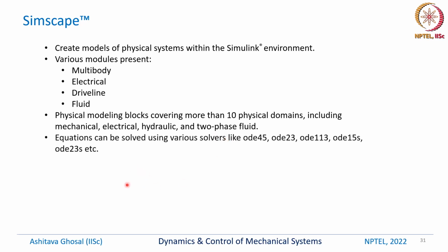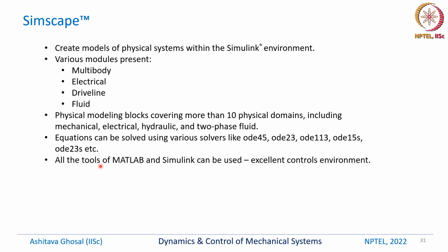The equations can be solved using various solvers: ODE45, ODE23, ODE113, ODE15S. This is a stiff solver. ODE23S is also another stiff solver. You can pick which solver you want to use to solve your particular model. And all the tools of MATLAB and Simulink can be used.